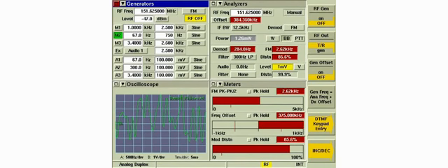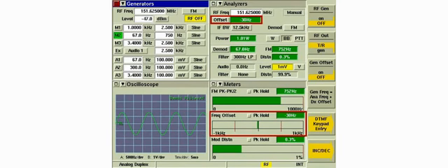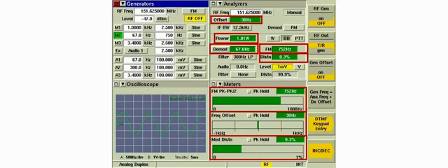Green indicates a passing value. When this radio is keyed, it is immediately obvious that the radio is passing all of the parameters of its test. When the radio is keyed, one can tell at a single glance that the radio has passed frequency offset, power, squelch tone frequency, squelch tone deviation, and squelch tone modulation distortion.